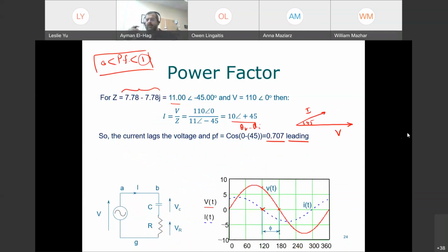So it is the zero crossing. Now we can convert that into the angle, and the angle is very clear. When we have the phase shift, if the current is negative with respect to the voltage, it means the current lags the voltage. If the current is positive with respect to the voltage, then it becomes a leading power factor.